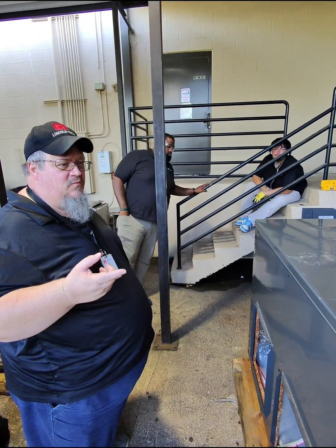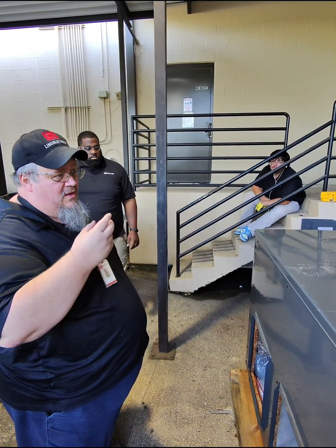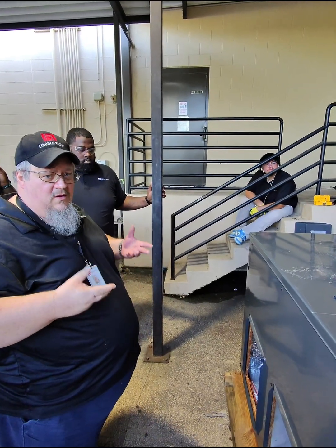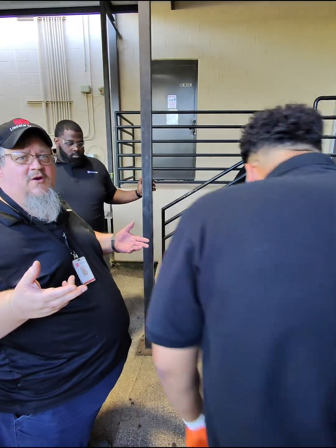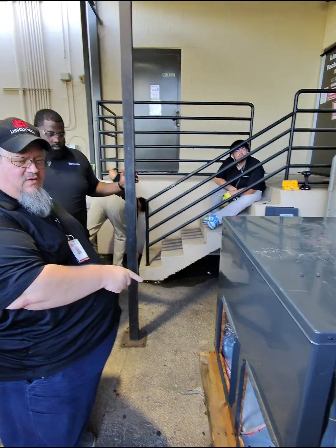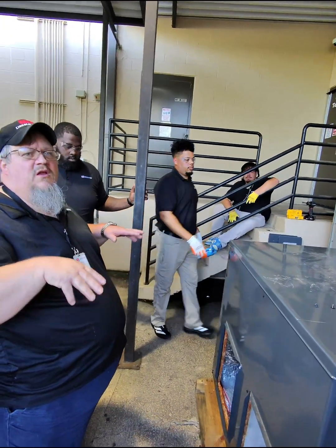So it's like a leak detection. If it senses a refrigerant leak in this system, we don't want electric motors and all that kind of stuff coming on and causing a fire, right? So what it does is if it senses that there's a refrigerant leak, it's going to shut your heating or your cooling down.